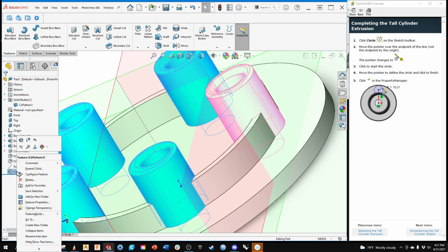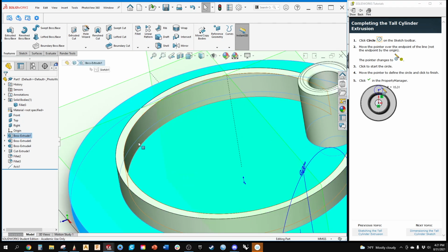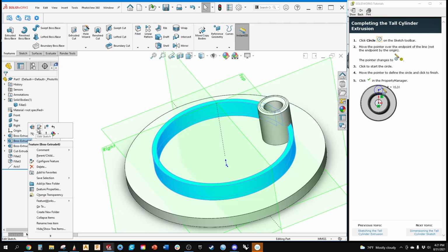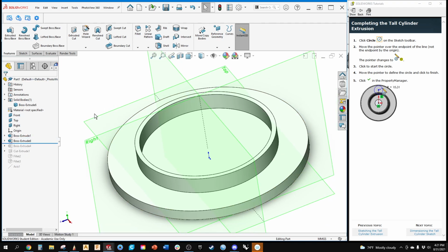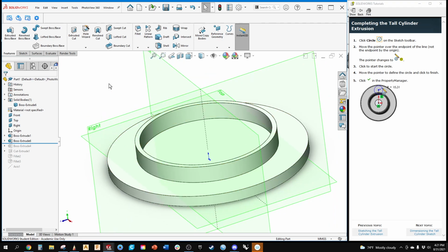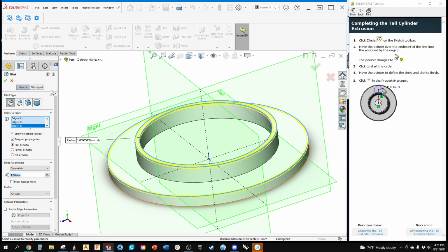Now, let's delete this. If I come back again, roll back up to this spot here, what I can do is I can put all my radiuses in first. So this is what I talk about, one of the things is when to put your radiuses in, what order. Radiuses don't always go in as the last item. So I'm going to come in, I'm going to put a radius here, and I'm just going to make them all 1 millimeter for all intents and purposes.